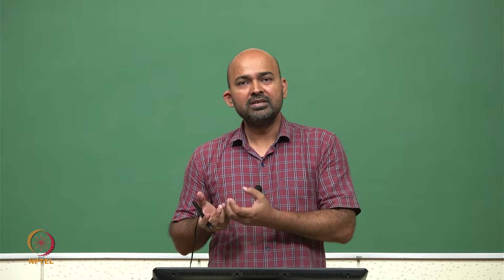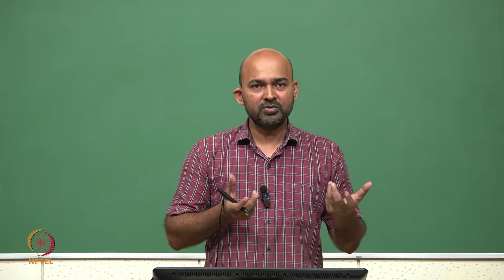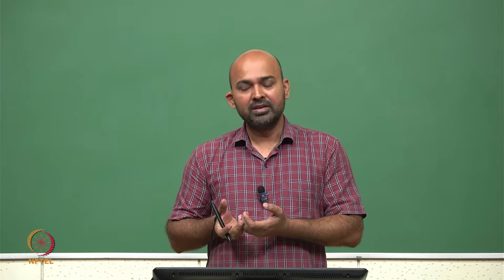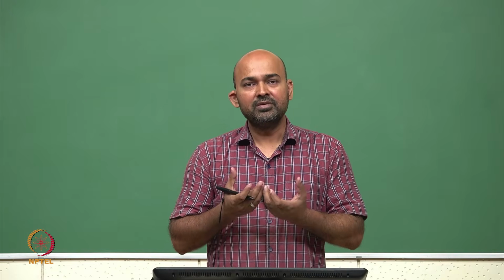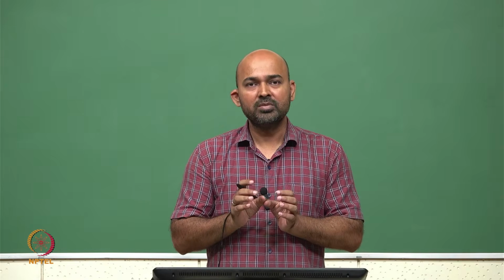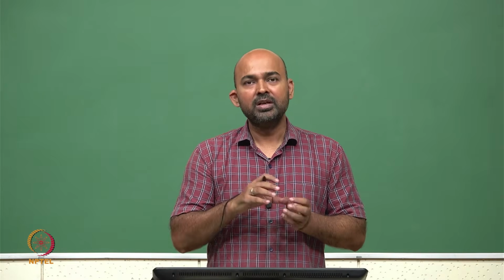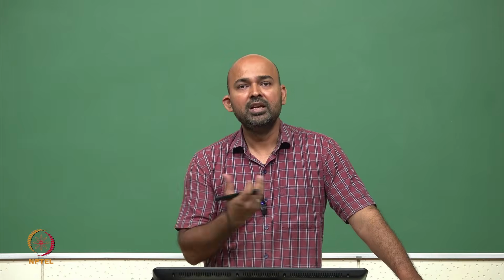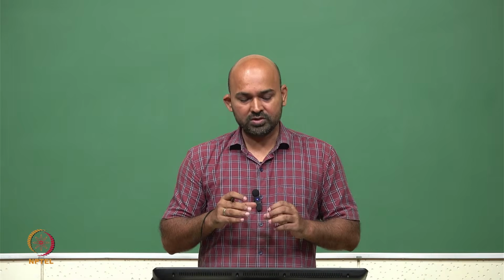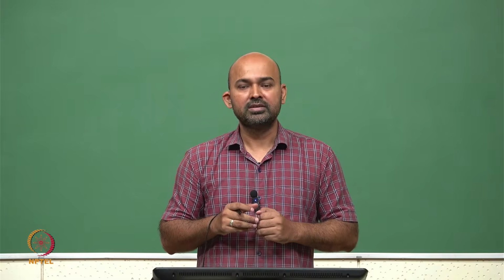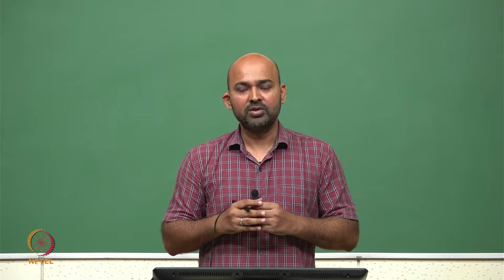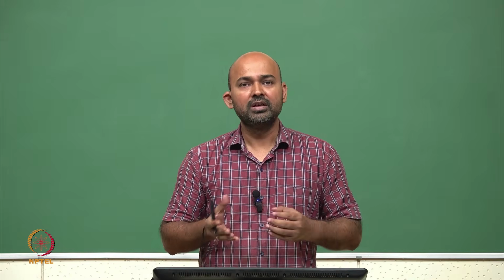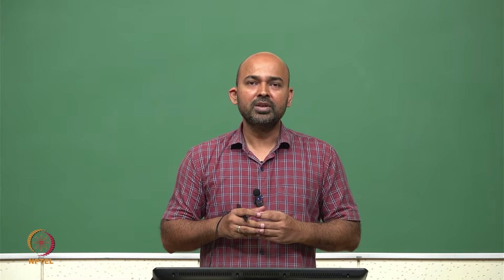This noise is undesirable, but because the adjacent wire is switching very fast, we have this noise present in the system or in the victim wire. So this C adjacent we want to keep as low as possible, so that there is no crosstalk noise between these two wires. We can play around with this C adjacent, or the capacitance between two wires, to reduce the crosstalk noise on the non-switching wires. So these are all the aspects we need to understand to make a good wire network in our PCB or on the silicon substrate. So this is all for today. Thank you.